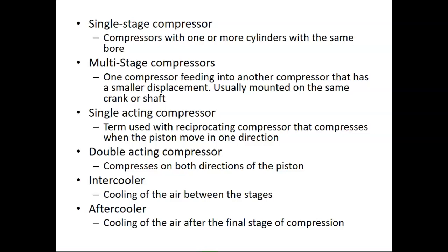This works very similar to that for single acting. For single acting, what it's doing is basically pulling it in, compressing it until it's compressed as much as it can before it forces the valve open and pushes it out. Only this is doing it far faster than you think. Double acting is doing it on both ends of the stroke. It's doing it on the in stroke and the out stroke.